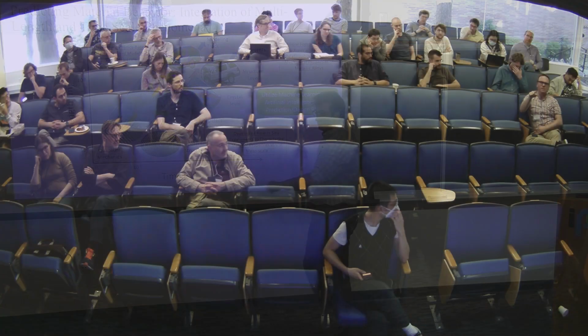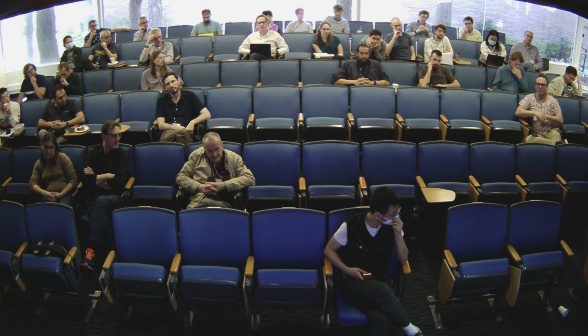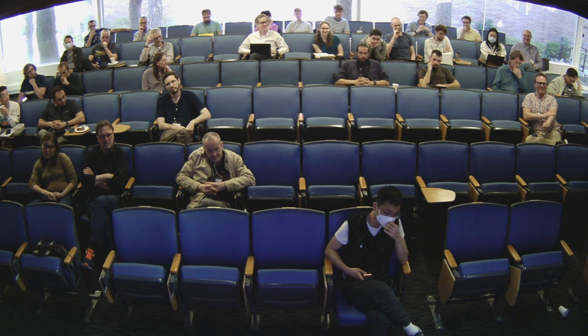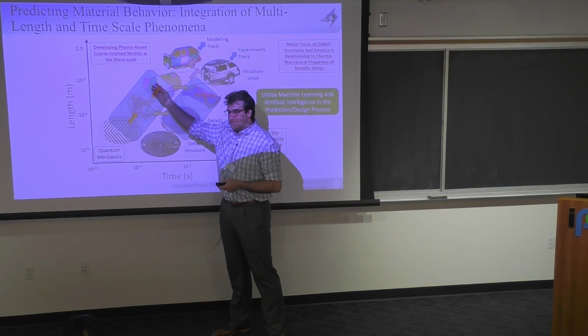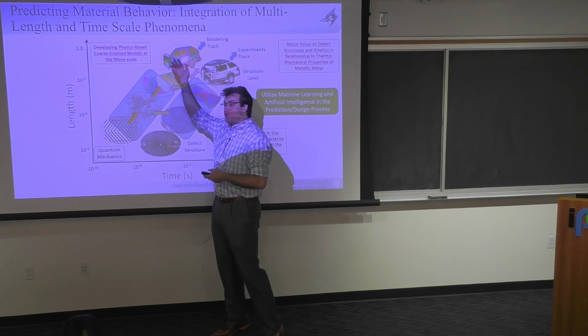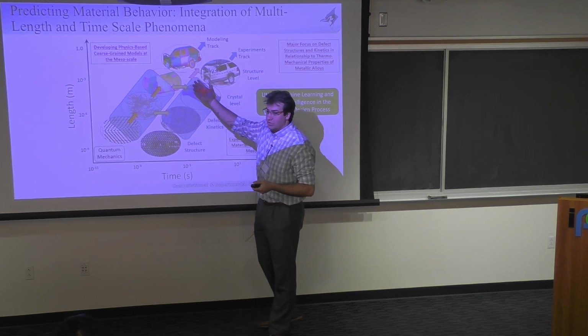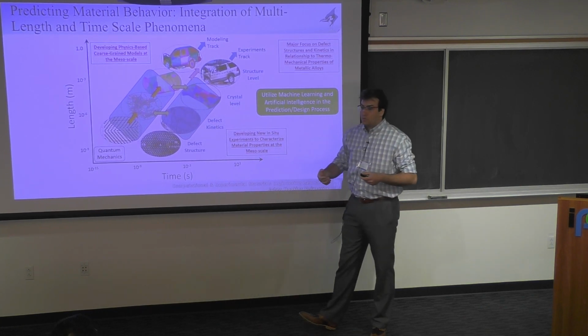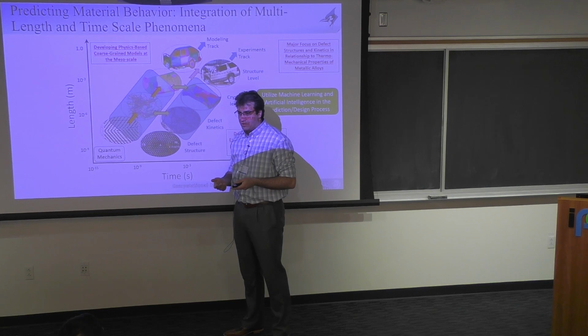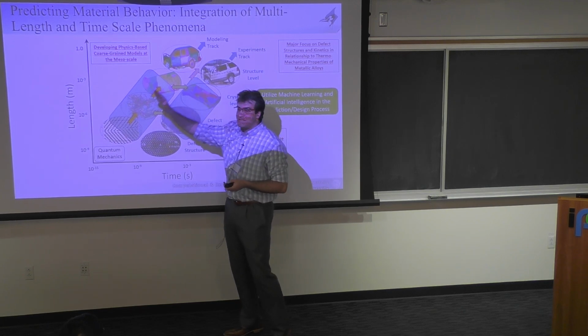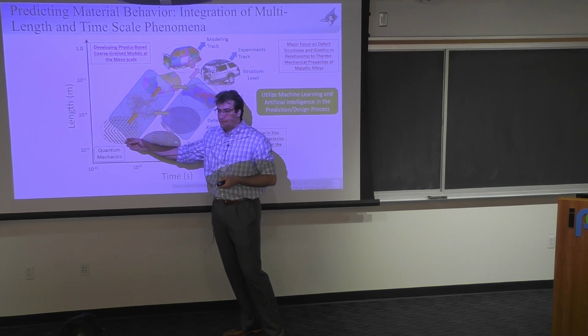Yes? From the crystal level to crashing a car, that's still quite a bit. Yes. So there are homogenization approaches that involve taking crystal plasticity level simulations and then trying to do large-scale FEM simulations. But now, empirical plasticity, not empirical based. So there are a lot of new techniques. There's the classical empirical approach, but the classical empirical approach does not take into consideration the microstructural influences.